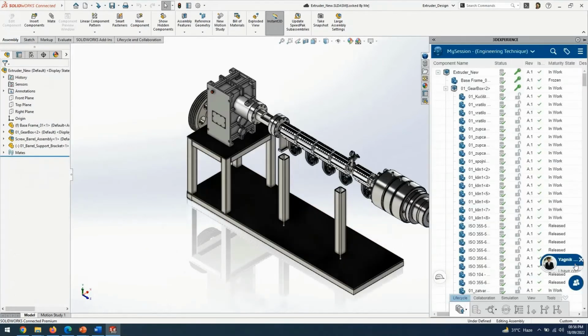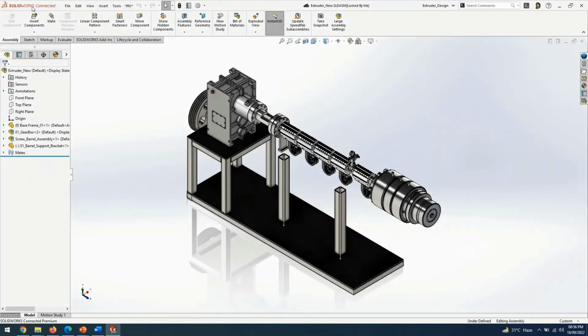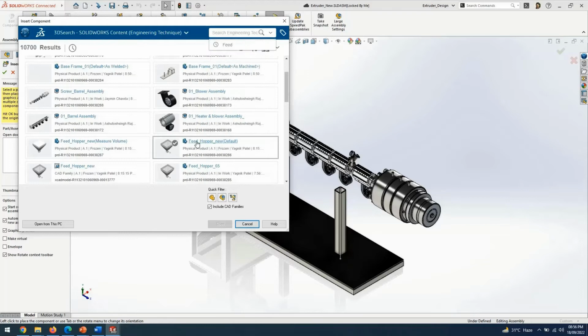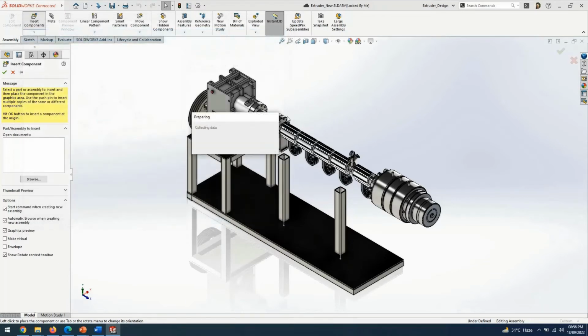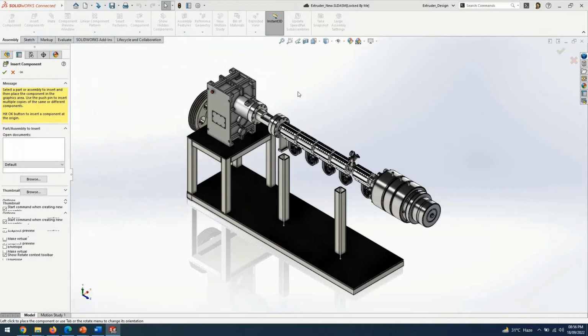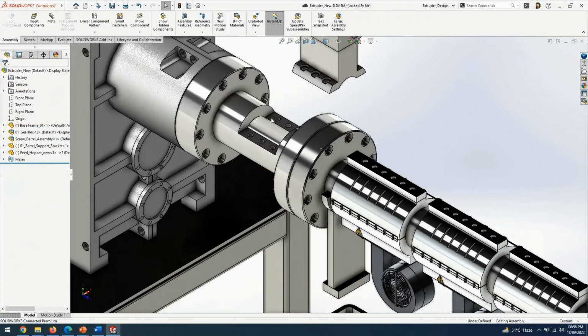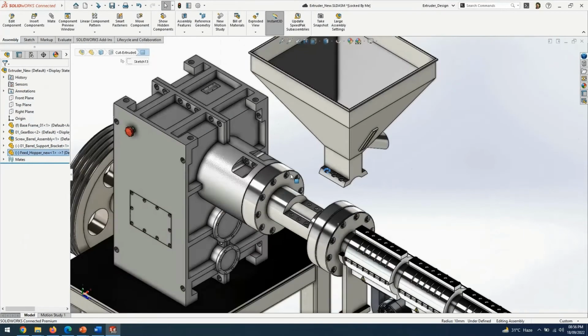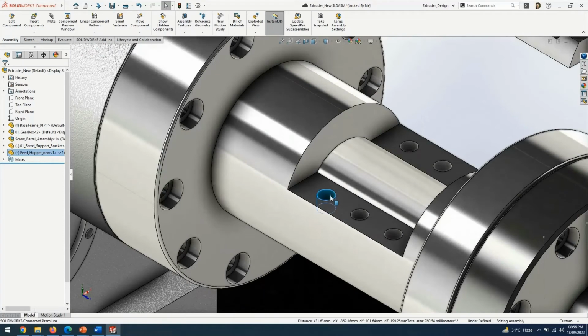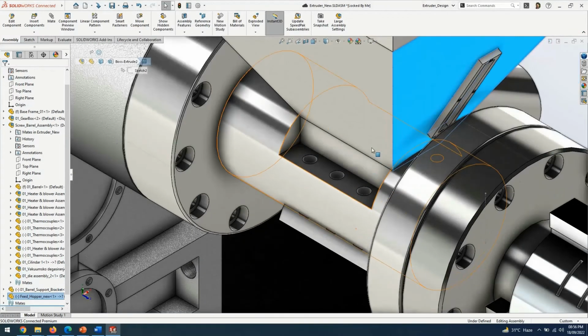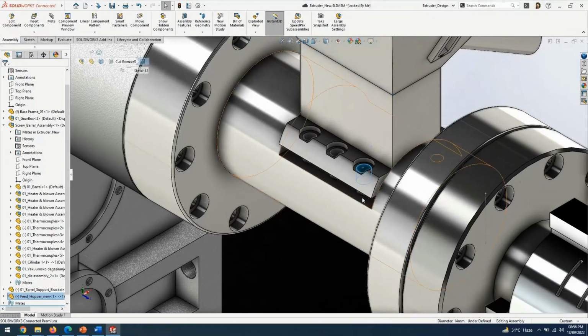While doing the same, he got the message that Yagnik has completed the hopper. So you can utilize this hopper and add the hopper into this assembly to see whether the hopper requires any revision or not. So starting by opening the hopper into the assembly and giving the required mates. During the whole workflow, all the mates have been assigned using the quick mate toolbar, which gives the user more flexibility to add the mates without going to the mate command manager.